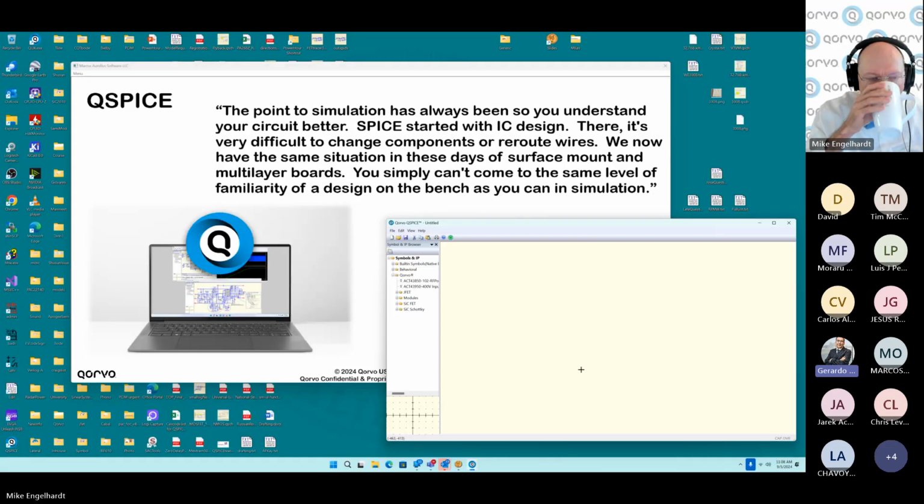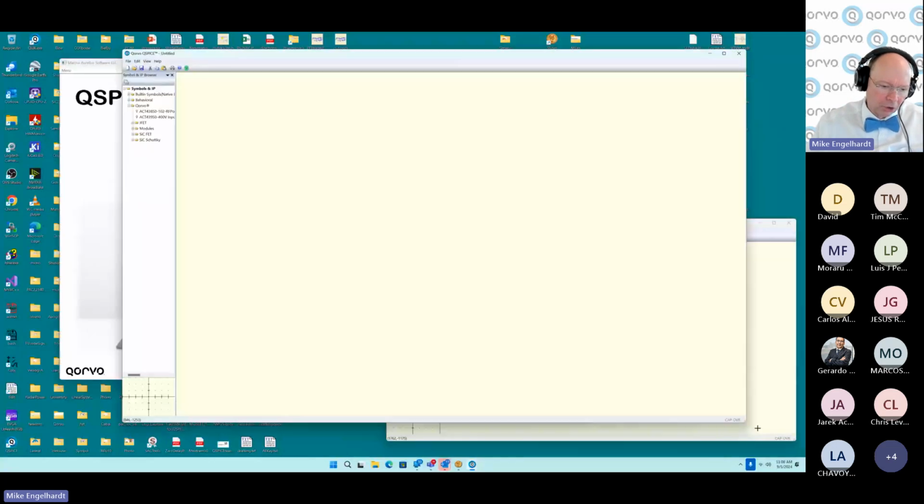It says, is there any special treatment that we need to do on QSPICE to get the power dissipation and temperature of the parts that you can simulate, including those? Okay, the way it handles power dissipation is different than what I've done before. In the past, I had the ability to plot the power flow into a component.